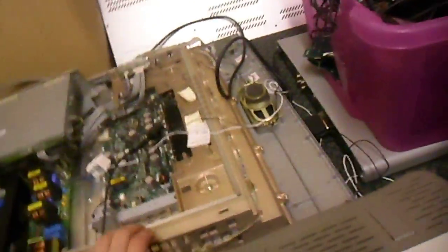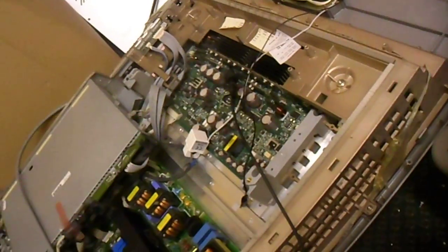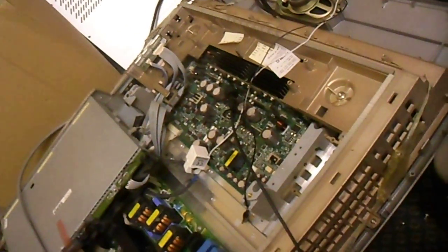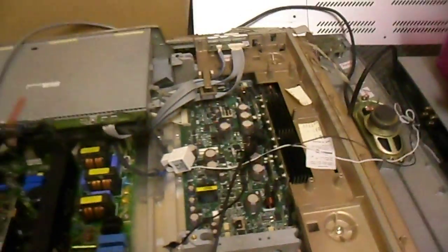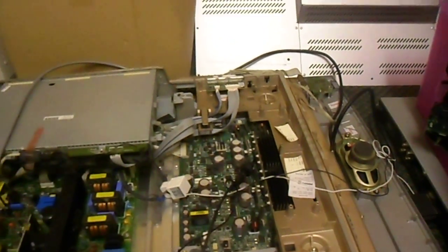This thing here is an EMI shield, because these older plasma panels produce a huge amount of radio frequency interference, and even with that metal plate that goes on the back of it to create a shielded cage to keep the noise out, because you've got these inductors over there and some over there which form part of the energy recovery circuit, and you're pumping plus or minus 100 amps into the panel during the sustain process.